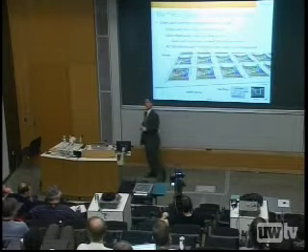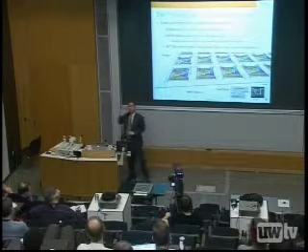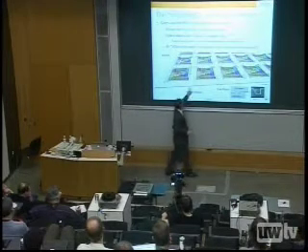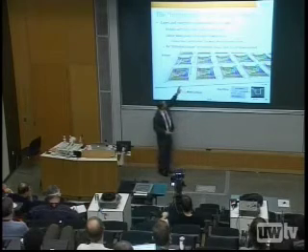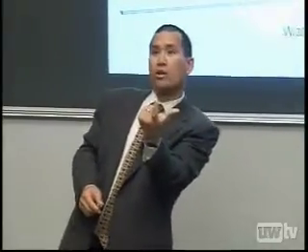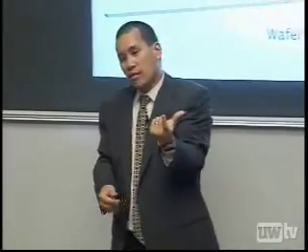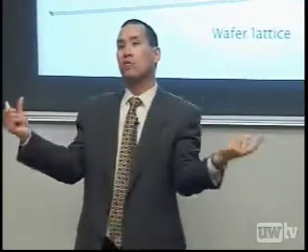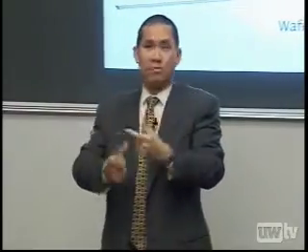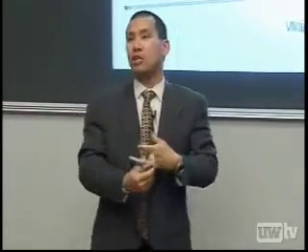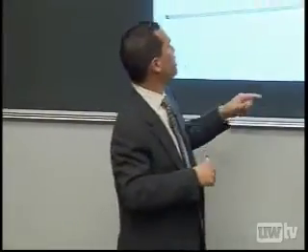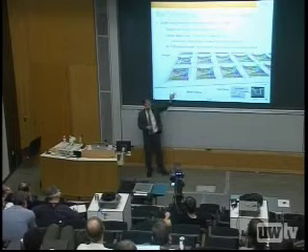Question in the back. What happens about the defect rate on the wafer lattice? Right. So my argument is that the wafer has nothing active on it. It's just passive waveguides, which are nothing more than silicon wires surrounded by silicon dioxide, and they're about 5 microns in size. So they're relatively large, relatively coarse. So yes, there will be a yield fallout from defects that are larger than that, but by and large, I have no transistors, I have no metallization, just photonic waveguides. And that's sort of key to the story here, because otherwise, this sucker would cost way too much.